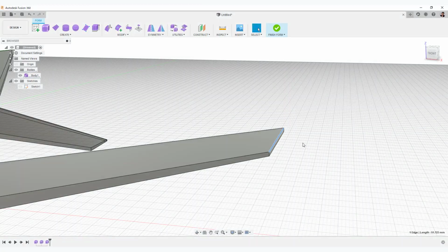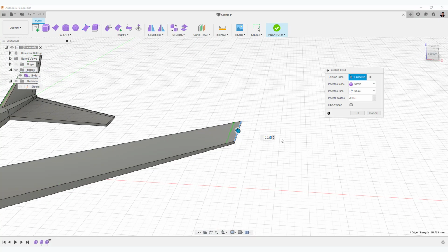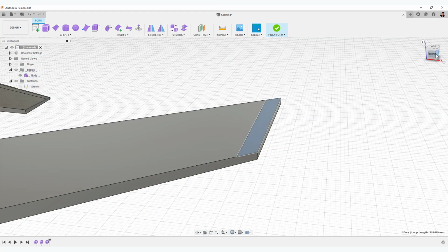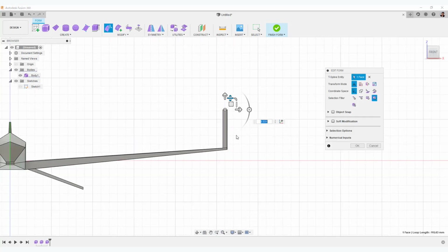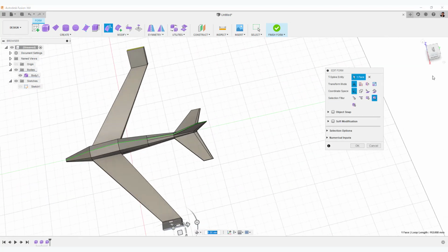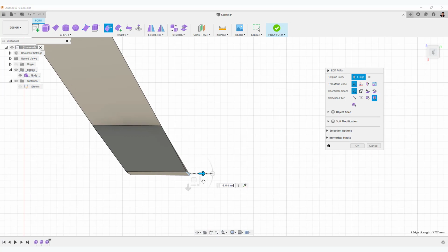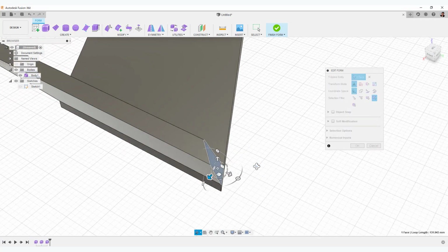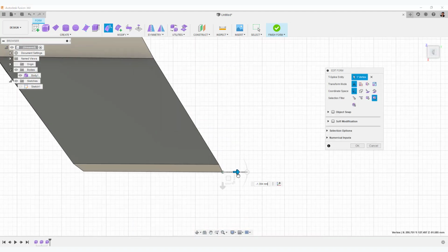Create the detail of the main wing. Select this edge, right-click to select Insert Edge. Select face and extrude upward. Make a taper on a horizontal scale, and move out to make an angle on the wing. Modifies the twisting of the surface.